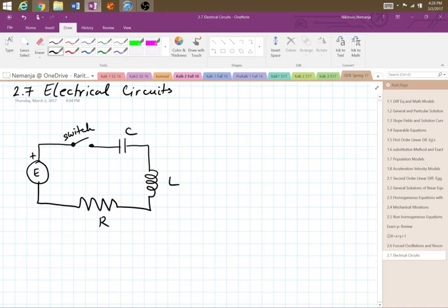It's not exactly what's happening, but we can think about it that way: each one of these components is going to use up some of that potential to operate. It's maybe the easiest way to understand what is happening. We call these voltage drops, and the sum of all voltage drops has to add up to the source, because the source is producing a certain amount of energy, and all of that energy is used in the circuit because there's nothing else hooked up to it.